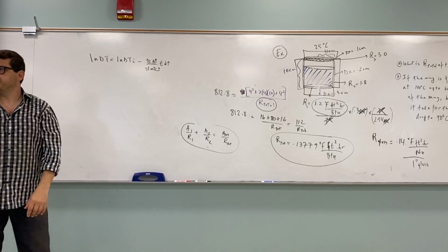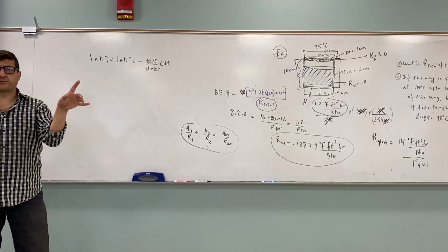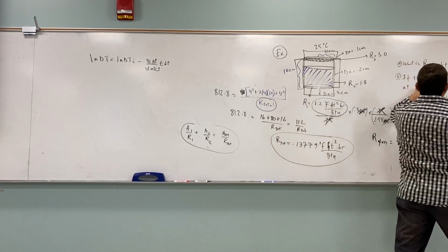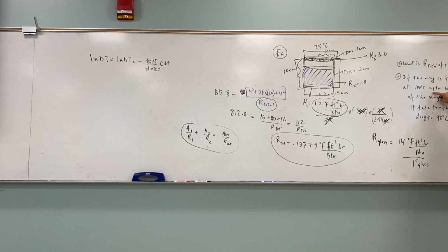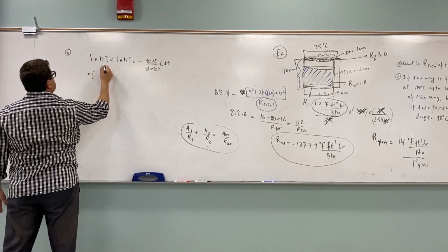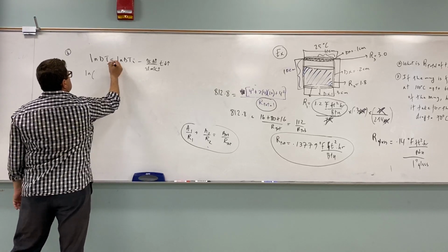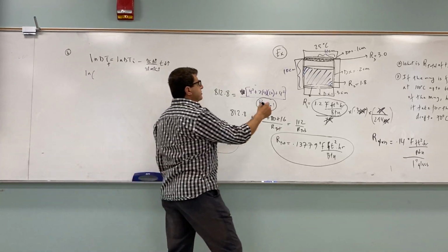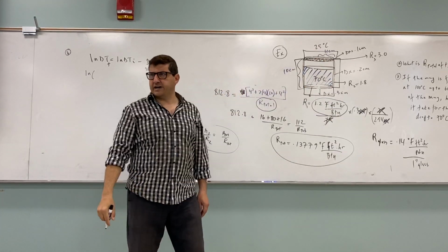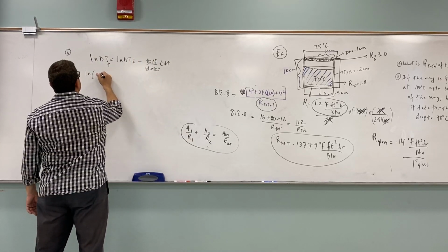Yep, that makes sense. Right, so we can go straight to Newton's law of cooling and then put ln delta T. So we want the temperature to go to what? 70 Celsius, right? And then the outside is 25. So that means we want the final delta T to be what? 70 minus 25, right? So that's going to be 45, right? So we put here 45.